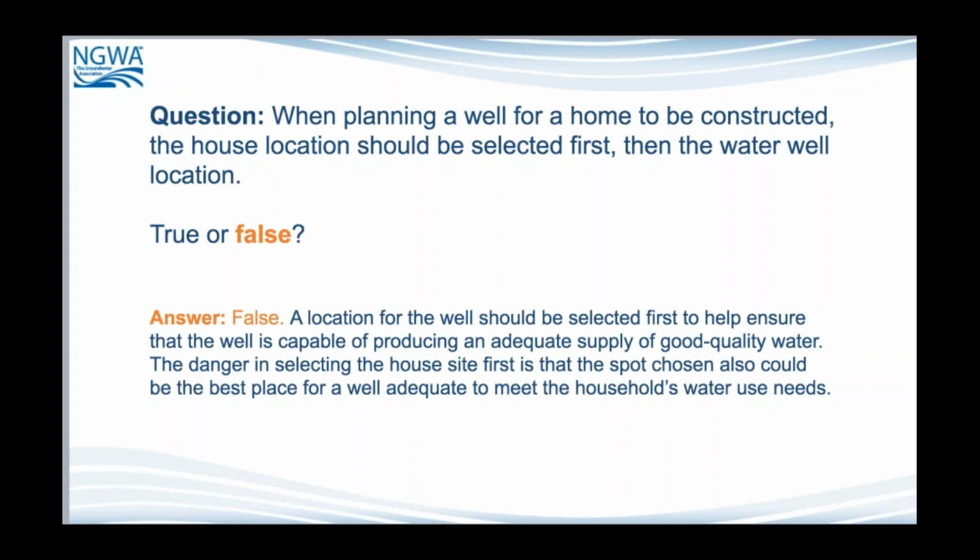So in the proper planning phase, yes, you do want to make sure that you put your well there before the house, but you also have to have some consideration at some point of where your septic is going to go. If you're doing a geothermal system, that's a little less critical as to where it's located. It still has to have a certain specific distance away from both your septic and your water well, but like I said, its location itself is not near as critical as your well and your septic.